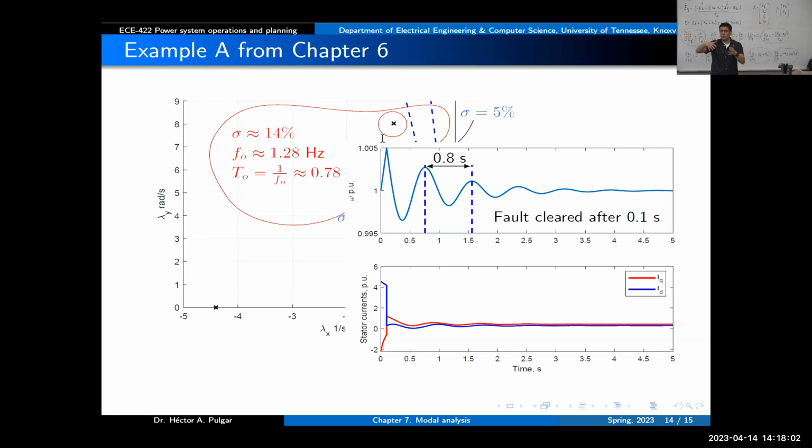When you have a second order system, typically they give you the description of the system in a standard form, where you have the damping factors and the natural oscillation, and you get some plots and responses, and you study the overdamped behavior. Do you remember that? Yeah, so all of that is in a standard form, and you use it. But in this case, what we use is actually the frequency of the oscillation itself. If that mode is excited, you should see that in the time domain simulation.